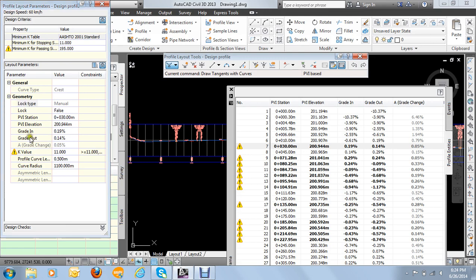Sometimes you design and you find a lot of errors, even though the grades in and grades out in the curves are according to standards. So when you find an error somewhere, first you have to check starting from the alignment as we did yesterday. Especially on curves is where there is a problem. You check the elevation, where you can change the radius or speed, things like that.